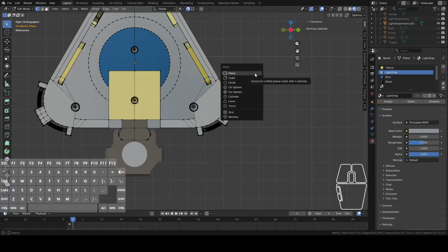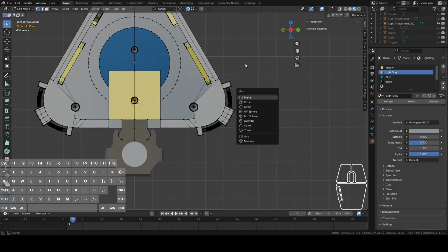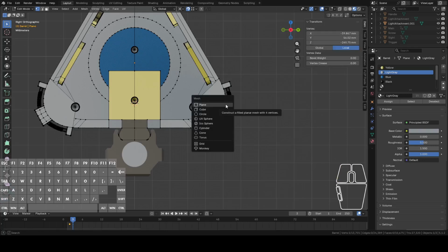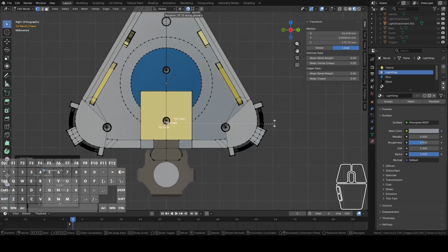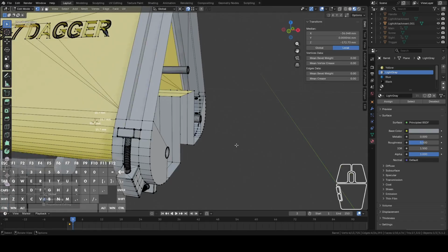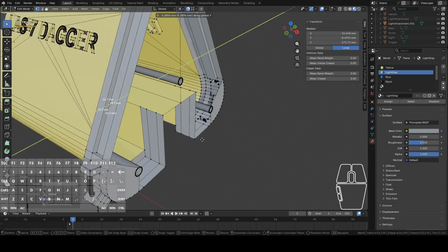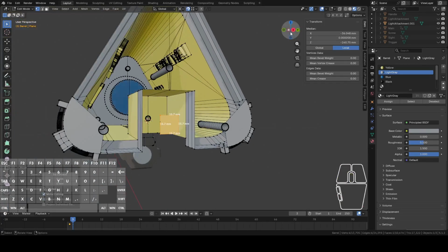Why can't I think of this? Yeah, Shift A. I guess I was holding on to that vertex. Not entirely sure why that happened, but anyway, we're gonna produce a square, and I'm gonna get this to rotate 90 degrees so it's flush with not that face. GX. Let's put it back here.